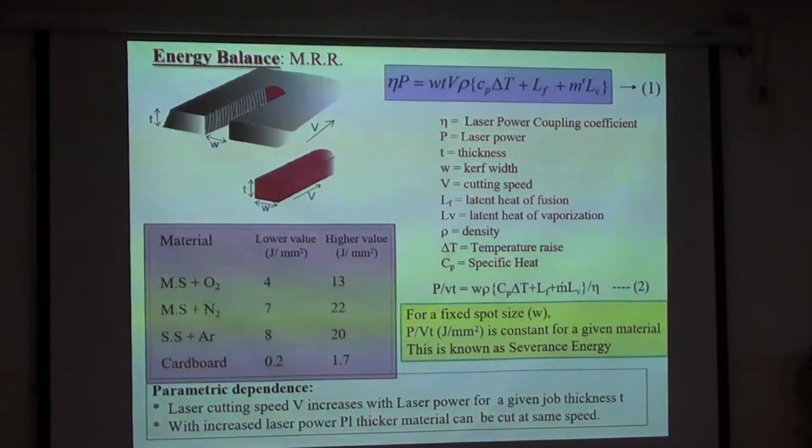It largely depends on the wavelength, also on the surface finish. So your surface finish is also very important. So next time if you say 200 watt or 300 watt, please ensure that you are talking about the absorbed power. It's not about the panel power. Panel power can be anything. But if your absorption rate is 50%, so your absorbed power is not 500 watt, it's 250 watt only. Okay. So this is your energy input.